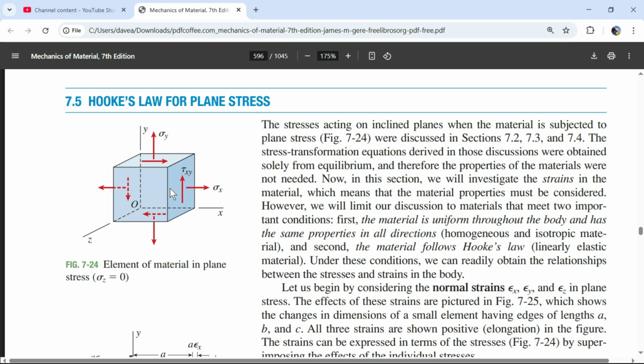Now, when it comes to shear stress, this is a stress with this arrow in this direction. It's on the positive x face, and it's in the y direction. You could also have a stress that's on the positive x face in the positive z direction. So this face could have two different arrows for shear, and every face could. You could have a normal and two arrows for shear. Normal and two arrows for shear. And even this face, we don't even have a normal force on it, but this face could have a normal and then two arrows for the direction of the shear forces.